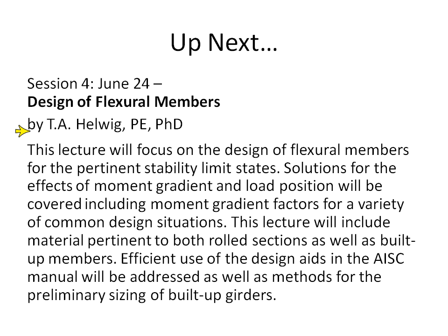It would only make sense: when you're hanging the load from the bottom, you're sort of pulling the member down and straightening it and trying to resist the LTB, whereas when the load's on the top and you start to get any type of out-of-plane movement, that load is even going to, almost through a second-order effect, accentuate that. So load placement is definitely important. In general, AISC doesn't account for it with its C sub B factor, but that's where they say, or by rational analysis. So you could account for the load placement through a rational analysis and use a different C sub B factor. But Todd's going to speak about that, I'm pretty sure, next week.